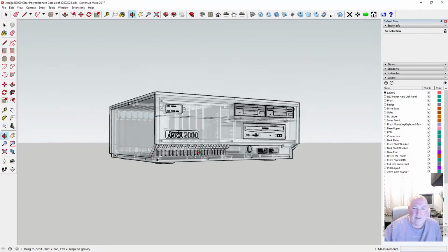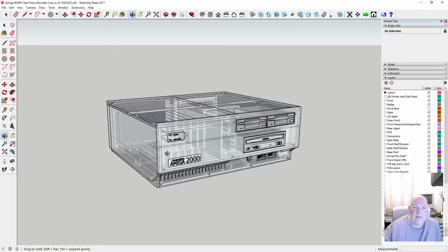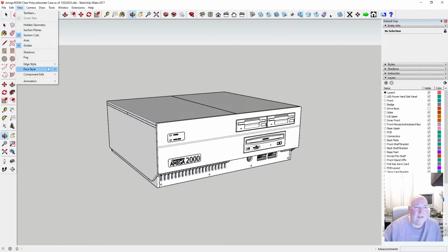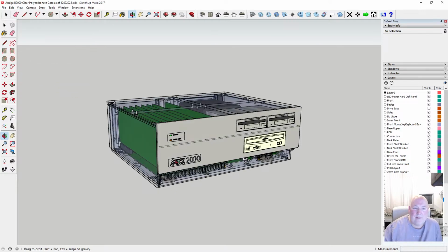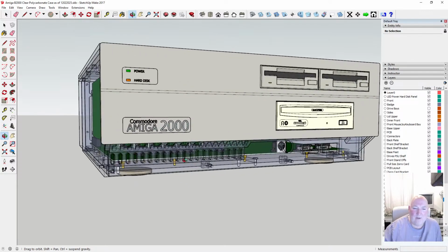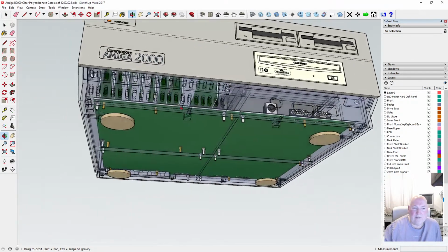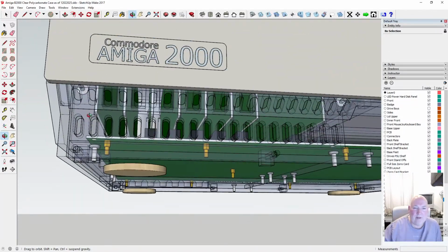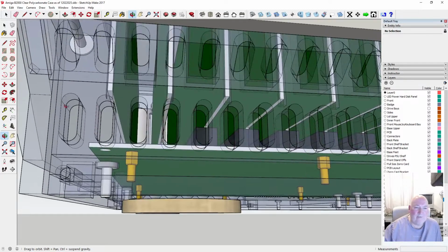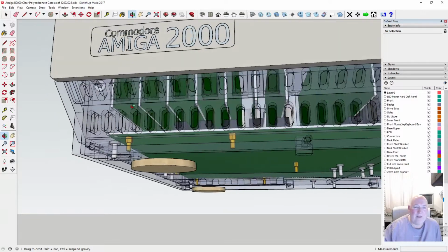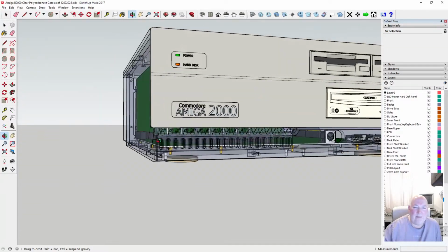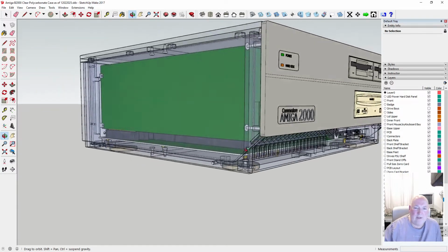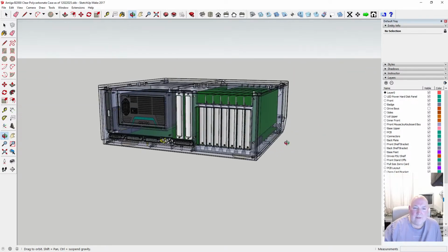Okay, so let's get back to the model, the other model. And let's get back to the right colours. Yeah, so just change it to white so you can see stuff, with it being clear, difficult to see. So we've got 20 now instead of 39, and they're 5mm wide instead of 3mm wide. So yeah, there's enough airflow, and it lets us do the G code. That's the main thing. Let's just do the G code.